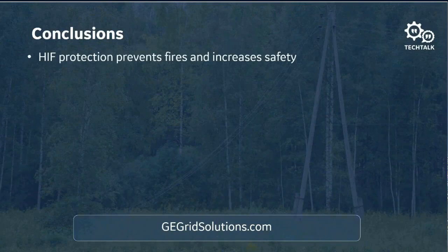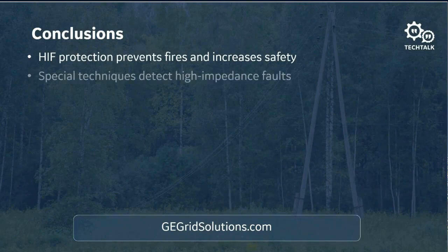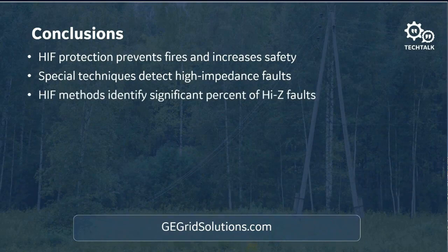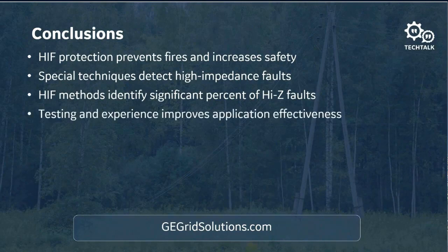In conclusion, we learned that HIF protection prevents fires and increases safety. Special techniques are required to detect high impedance faults. HIF methods identify significant percentages of high-Z faults. Modern methods are from 80 to 85%. And applying HIF protection takes some finesse. Testing and experience improves application effectiveness.